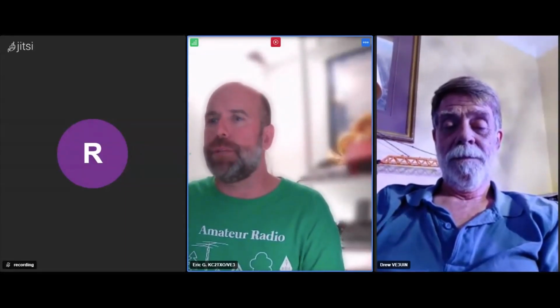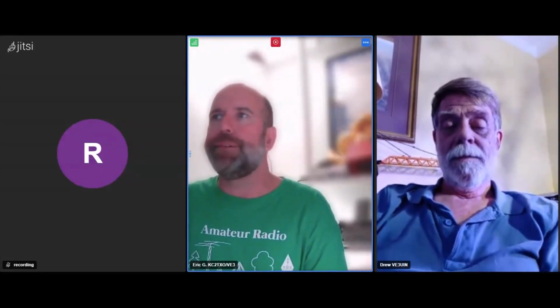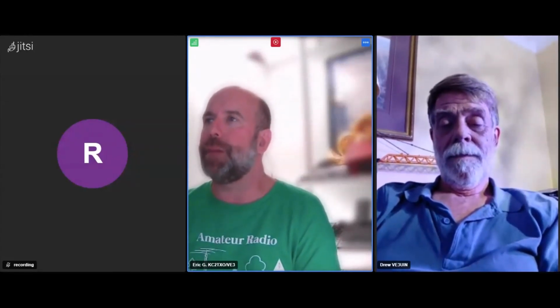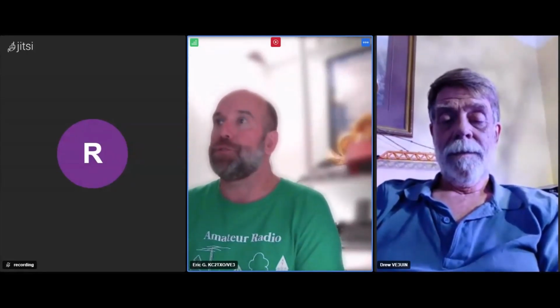Then we subbed in some RG8X, I think it was, thinner stuff. But it didn't matter what we did, we could not get the matching to be even close. We would have been happy with a 2.5 to 1 or 2 to 1. Do you have a dummy load?